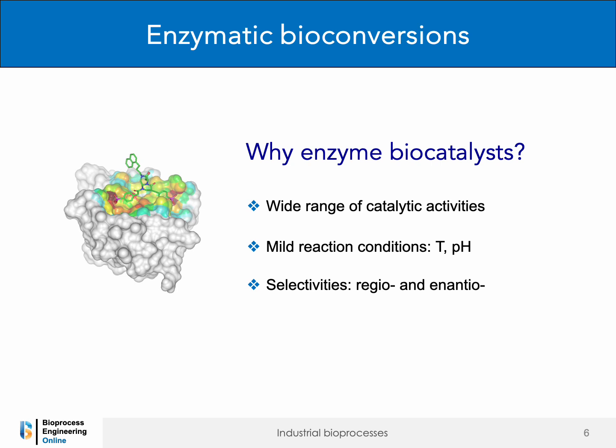The first category of bioprocesses comprises enzymatic bioconversions. In these processes, an enzyme protein catalyzes the cleavage or recombination of molecules. Enzymes hold industrial significance for their wide range of reaction activities in aqueous and non-aqueous media, and for their mild operation conditions such as temperature and pH. Moreover, their regio- and enantioselectivities make them particularly attractive for synthesizing chiral molecules.